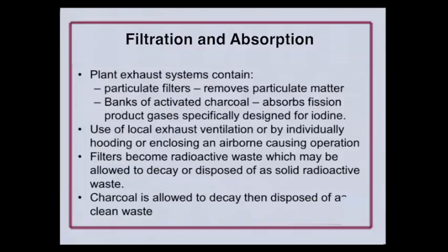And usually what you do is you just basically operate it. You can and do sample and monitor the radioactivity associated with it. But typically you can get so many cycles on a bank of activated charcoal until you have to replace it. What they'll do is shut it down at the beginning of an outage period and let it decay.